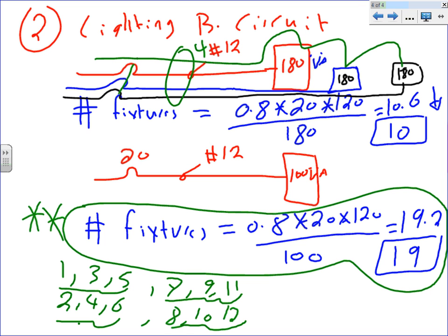Yes, sir. You drew out 3 rows of like 4 lights or something, across all 3 columns or rows, whatever. You'll obviously have whips in between. But how many J boxes will you have down the column? Will you just have the J boxes at the starting points and then move down?